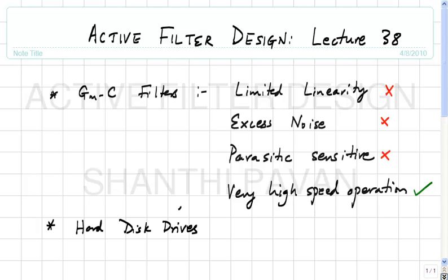Before you can get to the Viterbi algorithm, you need to amplify the signal, filter off excess noise, okay, then you need to have an A to D converter which can digitize this received signal to a reasonable resolution. It turns out that in disk drive systems, the SNRs are all of the order of 25-30 dB.